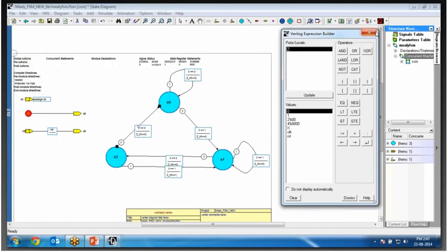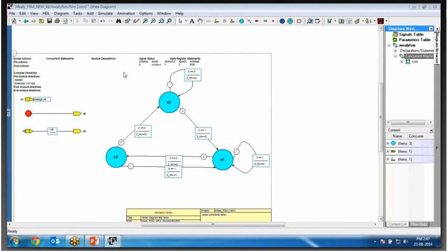So now you can see both the input and output here. Now this complete FSM is ready. That is, the Mealy FSM has been made ready for the 101 pattern. Both the FSMs are equivalent. The only thing is that the previous example was a Moore FSM. Now this example is for the same pattern, but it's a Mealy FSM. So now I am clicking on save.